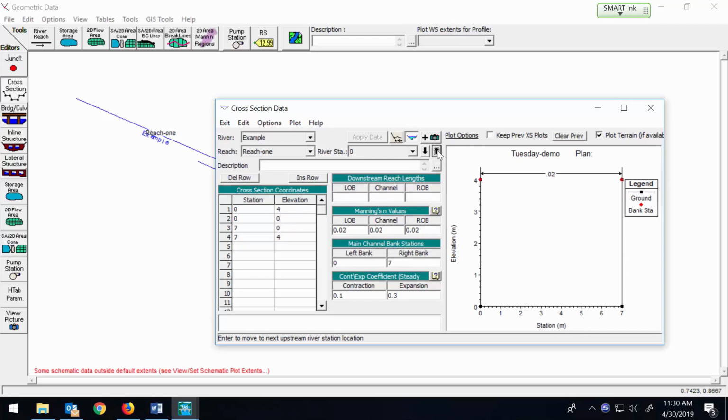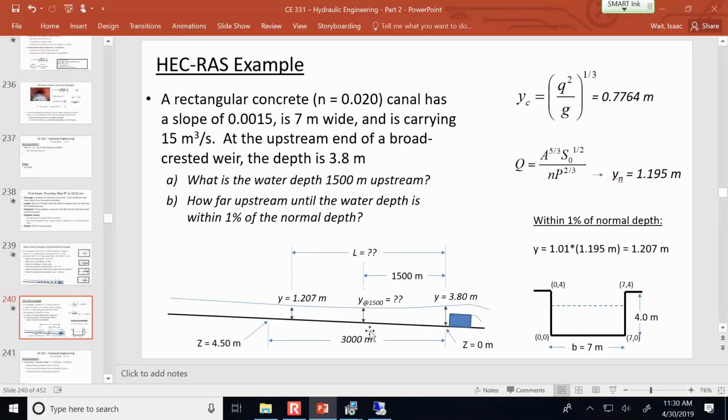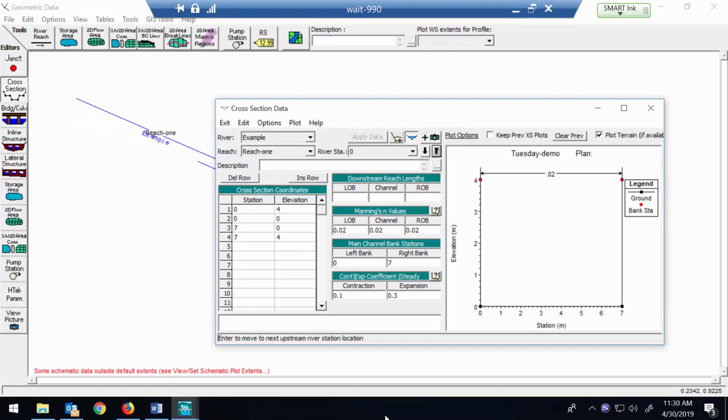But the nice thing is that the program will allow us to interpolate linearly between these 2 sections. So if I wanted to break it up into, well, what would make sense based on where we want to know things? If we do it in 300-meter segments, so if I wanted to break it into 10 segments, then I could type it in manually a bunch and have to continue calculating the delta z and all that. Or we can just see about interpolating it automatically.